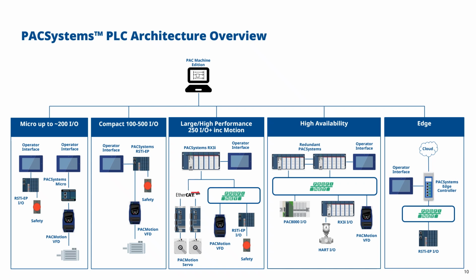So Modbus TCP would allow you to quote an operator interface with RSTi-EP I/O, and then you could also quote EGD using perhaps Versamax I/O or even PACSystems RSTi I/O, but by that time you're probably increasing the price of the system and the panel space, so RSTi-EP would be the way to go on that one. With the upcoming PACSystems Micro PLC, that will give you the option for a standalone controller with embedded I/O, and that also includes PROFINET support, so you could extend to PROFINET remote I/O including VFD capability.